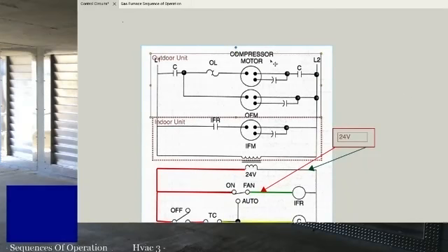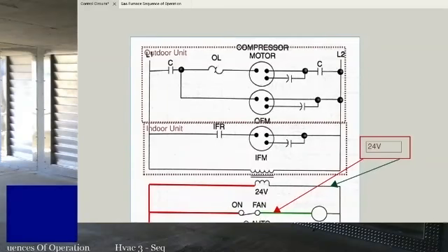On this, if you're somewhat familiar with contactors, you'll notice that on the outdoor section, they're showing a two-pole contactor. If we have black and red, let me go ahead and color a red wire. Say we're running our 240 volt, L1, L2.